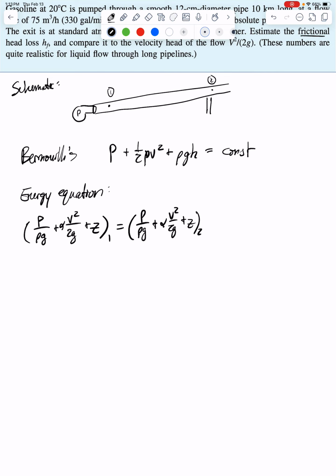And so hypothetically, let's say there's a pump sitting in between point 1 and point 2. This pump would provide additional energy, so point 1 would then get additional energy. Therefore, point 2 would have more energy than point 1. To consider this factor of the pump, we're going to subtract the height of the fluid column of the pump to account for the fact that with a pump, the fluid at location 2 will have more energy than the fluid at location 1.